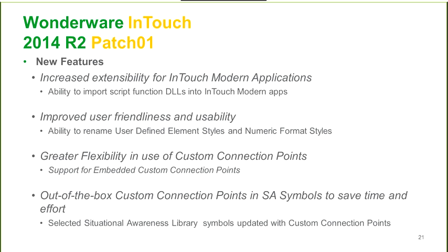We improved the user-friendliness and usability by enabling you to rename the user-defined element styles and also the numeric format styles. We have the custom connection points added. We put that into our situational awareness symbols to save you time when connecting the valves to the lines when you draw your P&IDs.